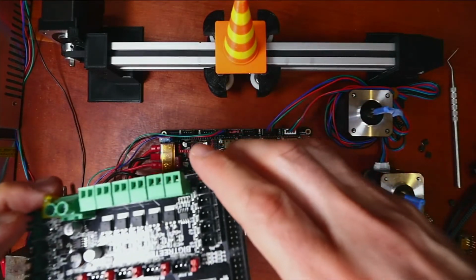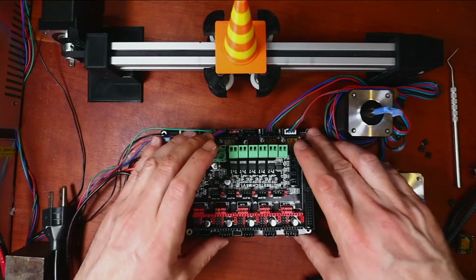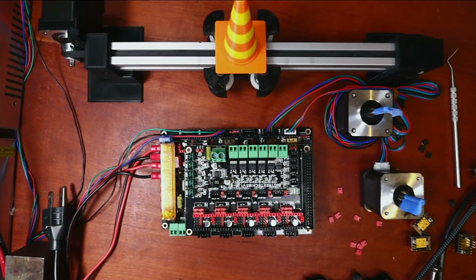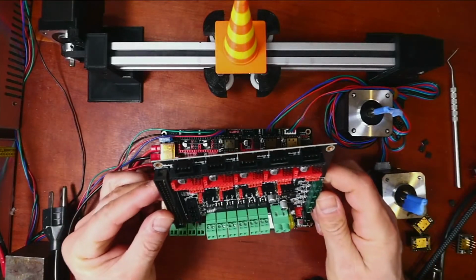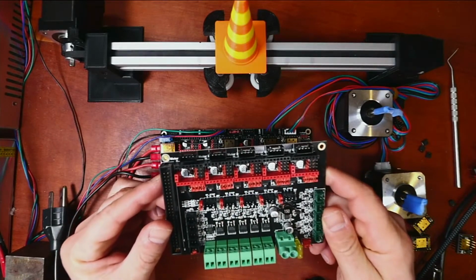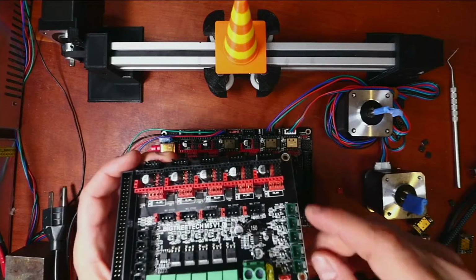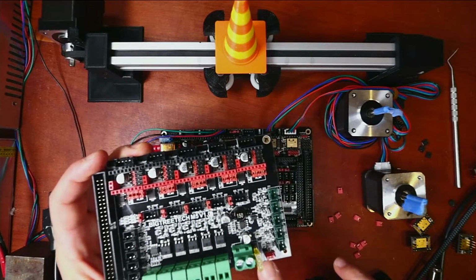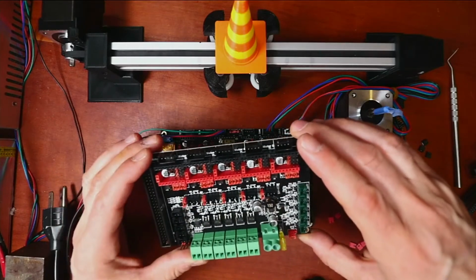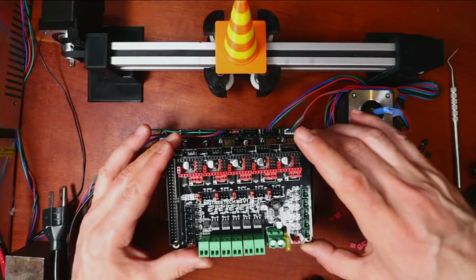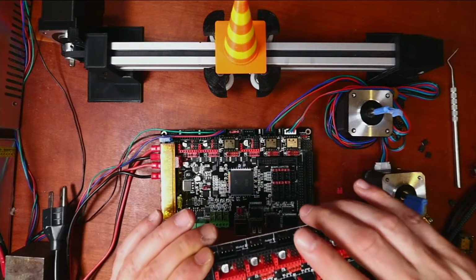Let me make sure things are powered down. So we have the M5 board. I'm going to have to look at the board in the right direction probably. And there is a jumper over here, like you said, that says 12 volts, and then VIN. I'm guessing that is possible. So it's default to 12 volts. We can actually test it.